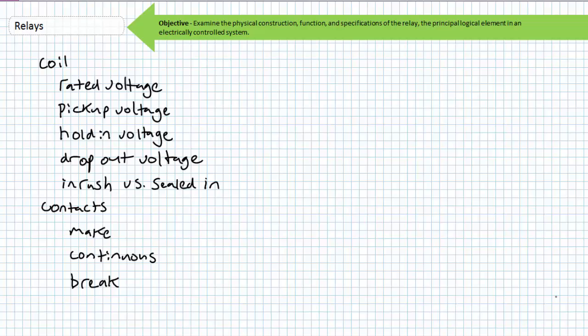A coil designed to run on AC cannot be used on a DC system, even if the DC voltage is much lower. A coil presents both resistance and inductive impedance to an AC waveform because of the changing voltage waveform. A DC waveform only experiences the resistive component, and current draw will be exceptionally high and damage the coil.